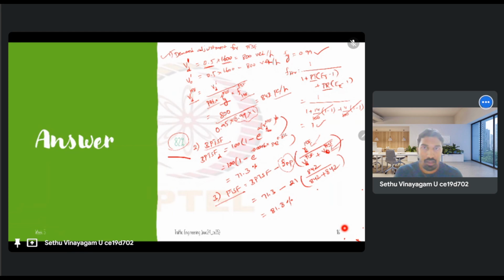So with this, if it is a class 2 highway, we can directly go for the LOS determination, right? But if it is class 1, this is one of the performance measures. The other, like ATS, we have to follow similar steps to calculate it. Okay, but here the question was only to find the PTSF, so we will stop here for this question.